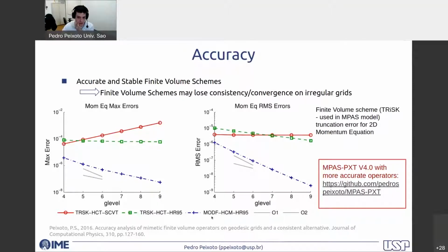There you can go up until this blue curve. So you do get convergence. There is an unexpected issue with stability that you get here. So you need to add more diffusion to control stability. So you gain accuracy and you lose a little bit of stability. There's always a duality on these low order finite volume schemes, where you want to preserve some mimetic properties that you have to deal with.